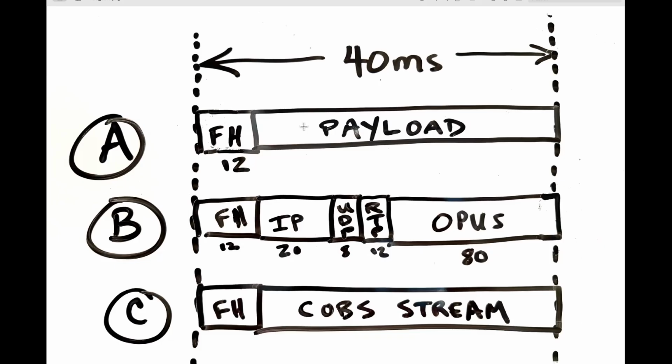The frame header contains the claimed station ID, which is encoded in 6 bytes and gives you room for about 9 characters of uppercase text and digits and a couple of punctuation marks, so you can make call signs out of it. And then it includes a 3 byte token, which is computed cryptographically, and it's part of the authentication protocol that we sketched out a few years ago for this whole system. So between having the sender ID and having done some previous cryptographic conversations with the sender, it can authenticate that each payload comes from who it says it comes from.